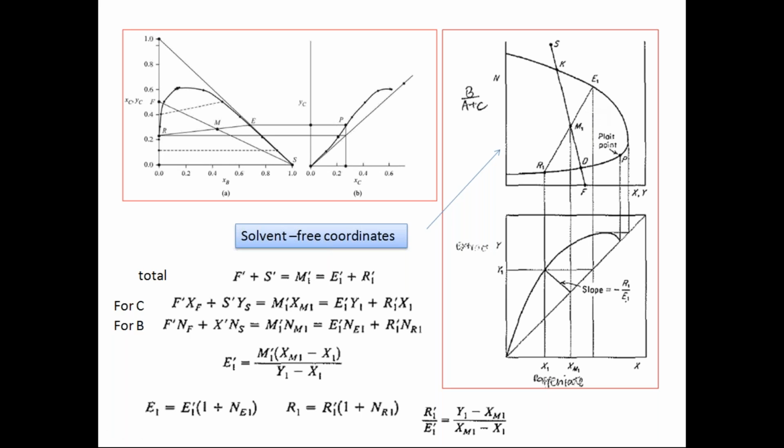You can use that and find out the required parameters, either quantities of the vapor phase and liquid phase, or quantities and qualities of the extract phase and raffinate phase can be estimated. With the material balance and also the solute balance, you can do that. However, you require the liquid phase diagram.